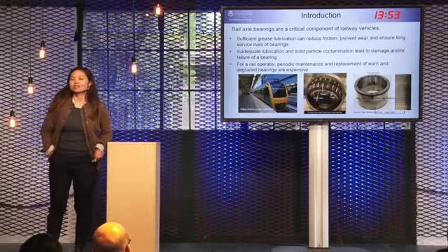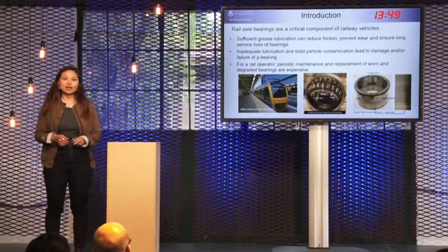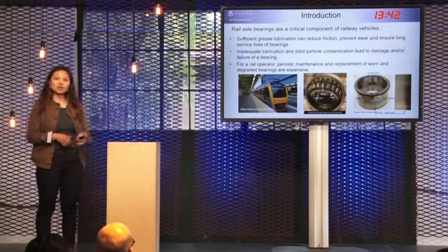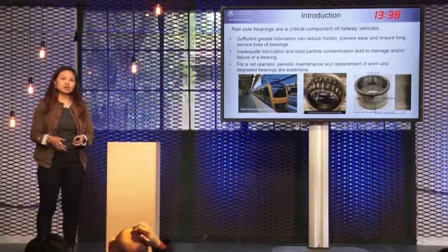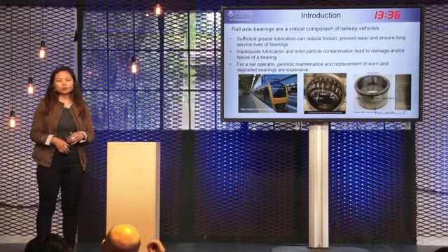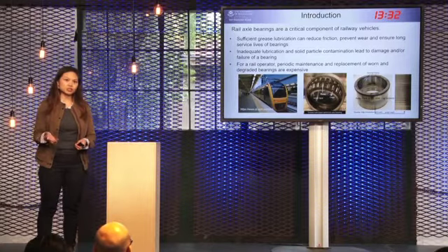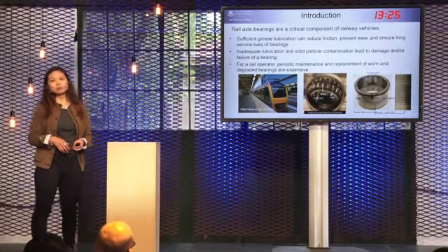In my group, we are very interested in looking at the hexo bearing because it's a critical component for the rail vehicle in terms of transportation safety. Lubricating a bearing with selected and designed grease will decrease the friction and wear, which will increase the long service life of the bearing.